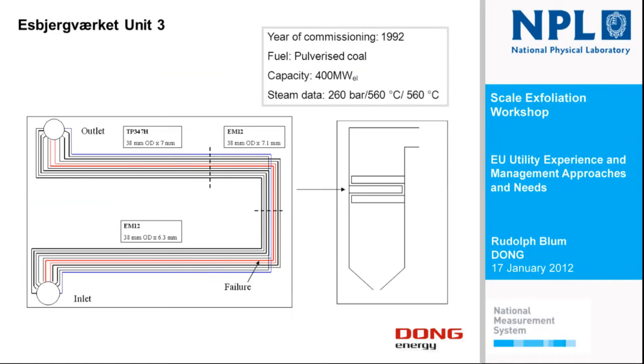By making some rough calculations, we found there was something tricky in this case, and finally we came to the conclusion that after 6 years in operation, all the austenitic parts had exfoliated or were in a condition for exfoliation. When you fill up the boiler with water, you rinse all the surfaces of the austenitic tubing of exfoliable oxide and bring it into the outlet header.